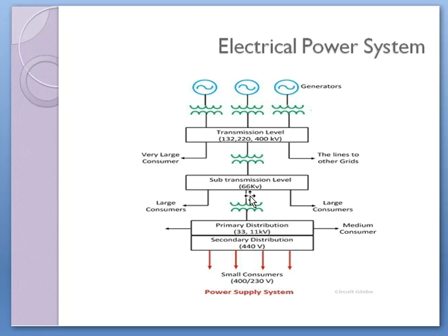So these sub-transmission level voltages are now taken into the substations, which are the primary distribution stations, where these voltage levels of 33 kV, 11 kV are directly used by the large industrial consumers, or they have to be again reduced to lower levels of 11 kV, 440 volts and so to be used by the small consumers, the households.